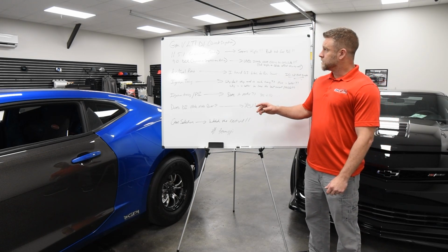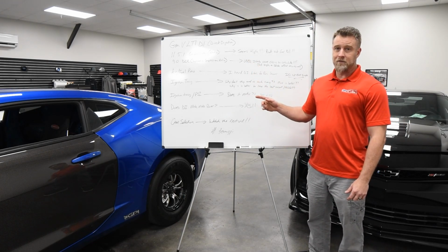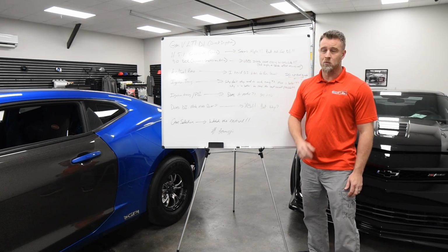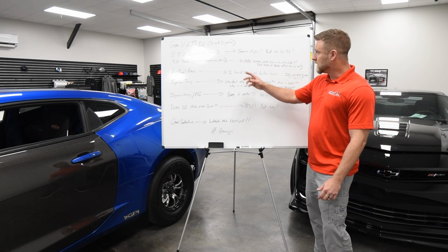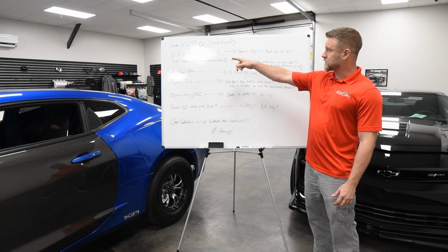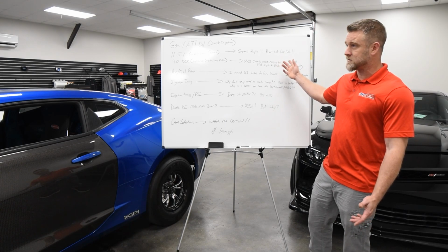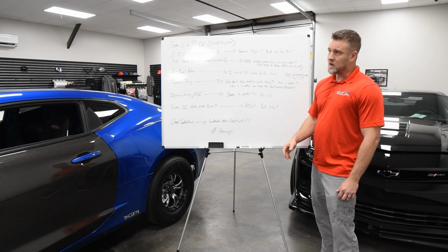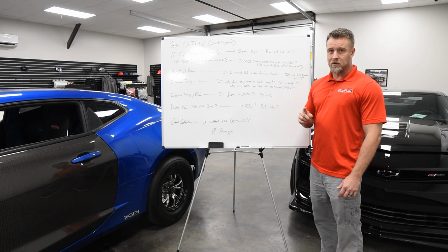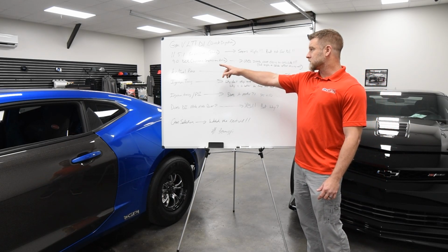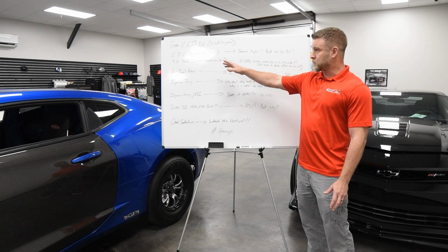First thing that stands out with the Gen 5 LT engine, obviously, is a lot higher compression than our normal LS stuff from the factory. And 11.5 to 1 compression seems really high for a pump gas engine from the factory, but not necessarily for direct injection engines. So it works out to be about 9 to 1 dynamic compression.